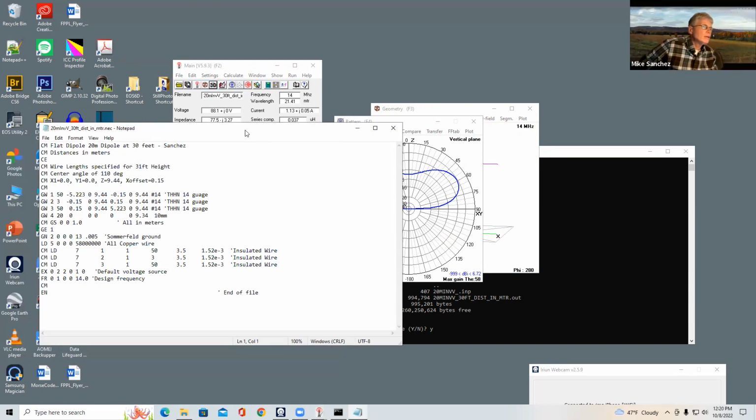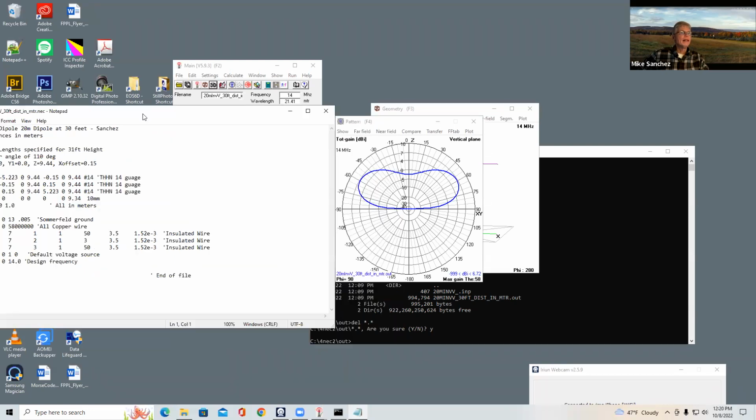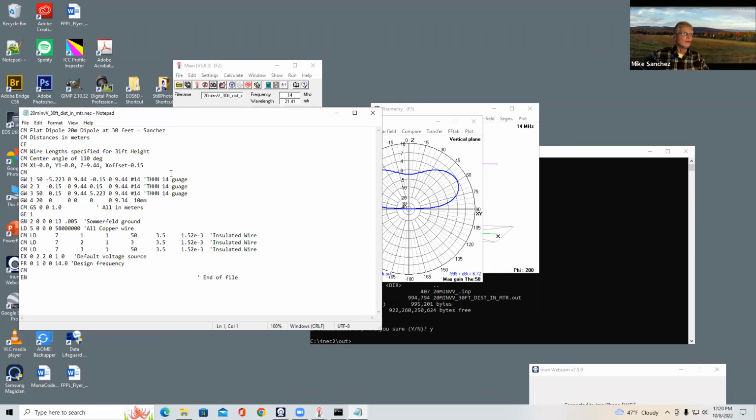Right, so the ends of each of the wires have to be aligned exactly. As we briefly talked about, in the left wire we have minus 0.15, and then the center wire has to start at exactly minus 0.15. If you end this guy at 0.16 and start this guy at 0.14, they're overlapped and you'll get an error.